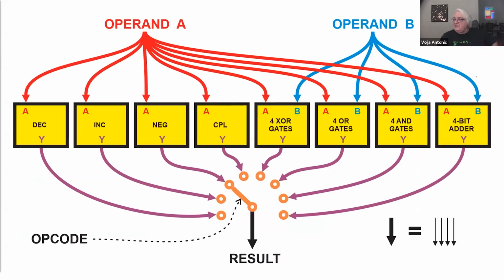Now you should imagine some other circuits here. The rightmost is the adder, a 4-bit adder. We've just talked about it. You can only put 4 AND gates. You see, all of these circuits have 4-bit inputs and 4-bit outputs, if it's a 4-bit processor, of course. And you should imagine this in 4 layers. That's why these bus lines are so thick. This one and the output also. They actually contain 4 single lines.